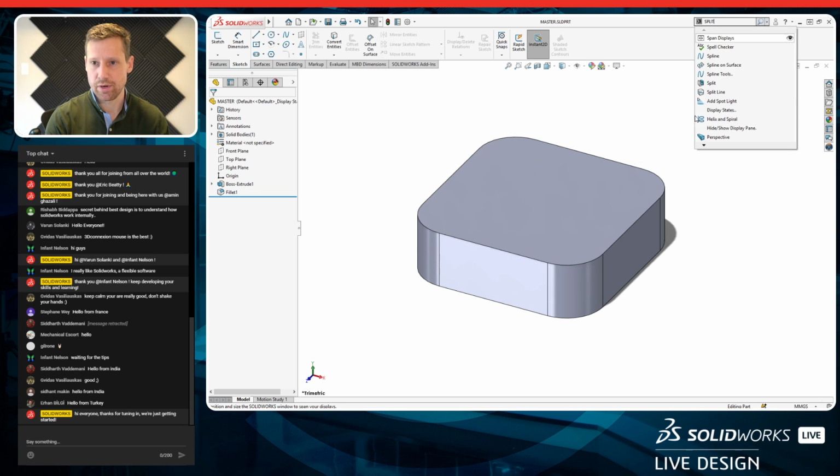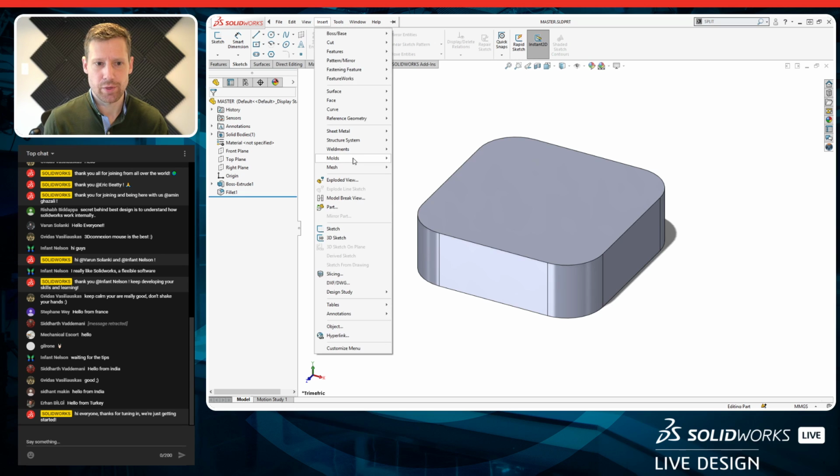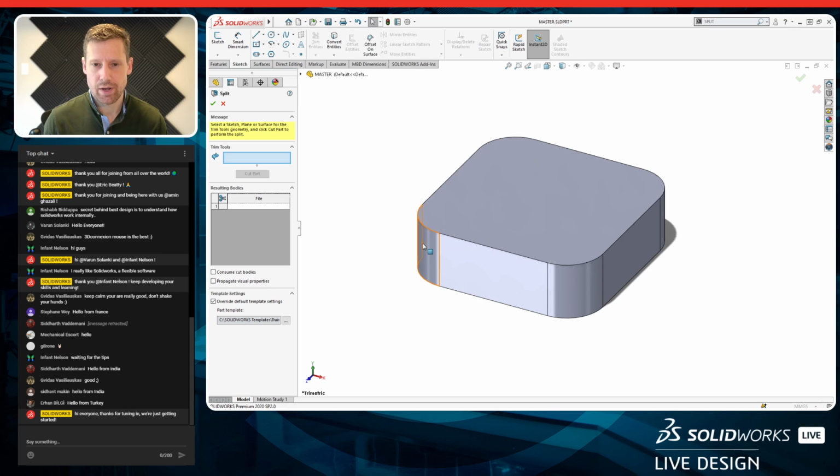So I'll type split here, and it'll filter down all the commands to just the ones that have that in there. Now I could hit enter and just use that top command, but if I want to know where it is for later, I can just use this eyeball here and it's going to show me exactly where that tool is located. There we go. So it's buried in this menu under split. If I use that often, I may want to add that to a context toolbar or something like that. But for now, I'm only going to use it this once, so we're good.